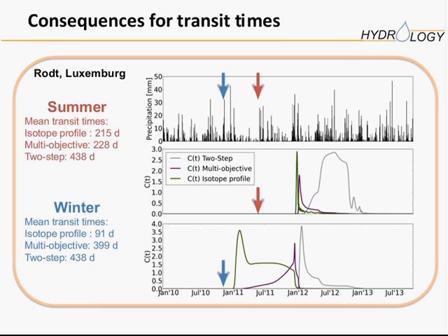So the water vapor you extract from the soil is always very close to saturation, and that's actually the problem that we mostly have. If you do not dilute, you always have condensation, which is the worst thing that can happen, because then you have that water sitting in the lines for a very long time.